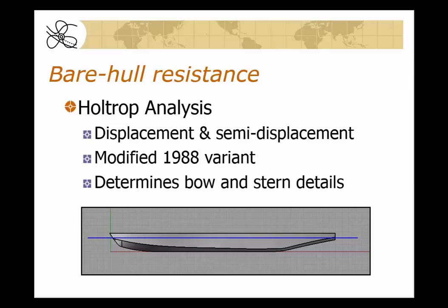The Waltrip analysis. Now, this is for displacement and semi-displacement hulls. I made mention earlier to what was called a CT-based calculation. Unlike the Savitsky, which is a solution of forces and moments, a CT-based is the traditional Froude scaling approach, where you have residuary resistance, C sub R, plus frictional resistance, C sub F, equals total resistance, C sub T, in coefficient form.